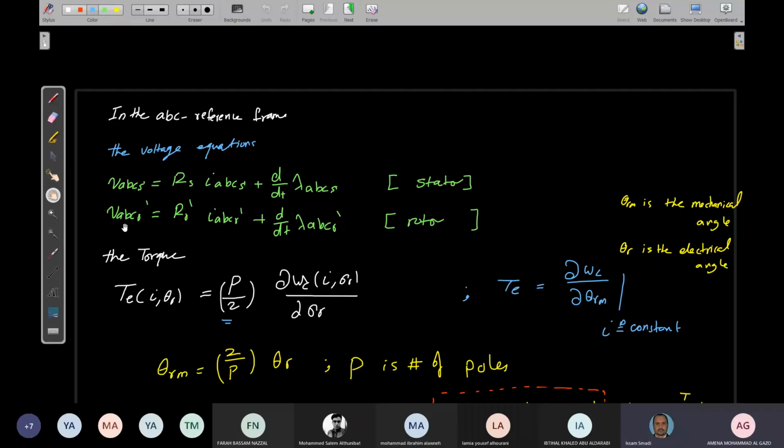Now you know that more phases, more power. Now the single phase system, for example, has two shortcomings. The first one, there's no starting torque. And the volume per torque is small, which means that if I need 1 horsepower single phase, and I compare it to 1 horsepower three phase, I can find the three phase is more compact.